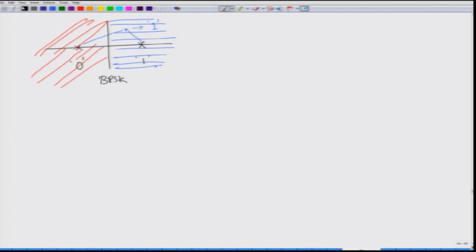But interestingly, if you have a BPSK transmission and then you have some phase noise, what would the phase noise do to the BPSK signal? It starts to rotate the constellation points. So, the received signal can lie anywhere on this circle depending on how strong your phase noise is. To completely cover the circle, the phase noise has to be large. If the phase noise is not very large, then it would be only over one particular section. So, let us say over this segment your received signal can lie anywhere, but still notice that you are not making any errors here.